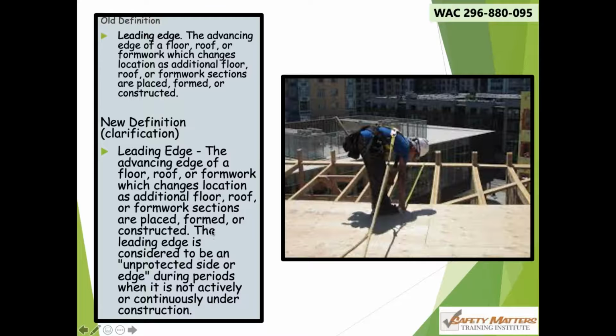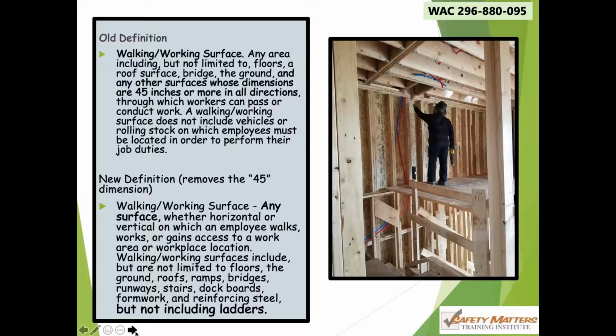And then they've added this. The leading edge is to be considered an unprotected side or edge during periods when it is not actively or continuously under construction. So if a leading edge is an unprotected side or edge, that means when it's not being continuously let out, when we're not performing that activity, we need to protect it. This was one of the biggest changes that was talked about in 2017.